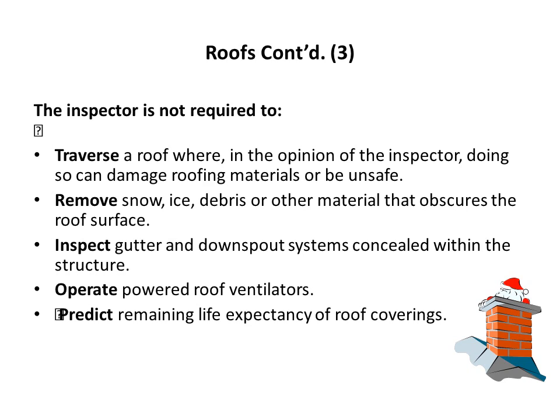The inspector is not required to traverse a roof where, in the opinion of the inspector, doing so can damage roofing materials or be unsafe. Remove snow, ice, debris, or other material that obscures the roof surface. Inspect gutter and downspout systems concealed within the structure. Operate powered roof ventilators, and predict remaining life expectancy of roof coverings.